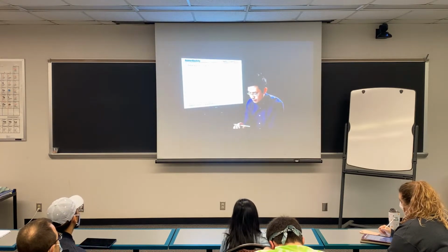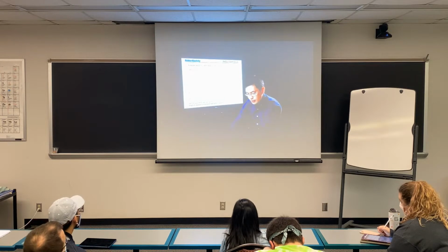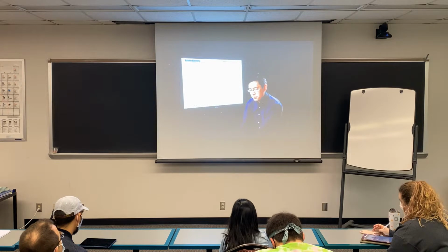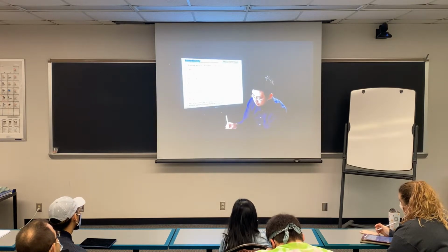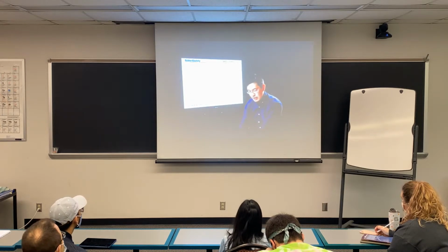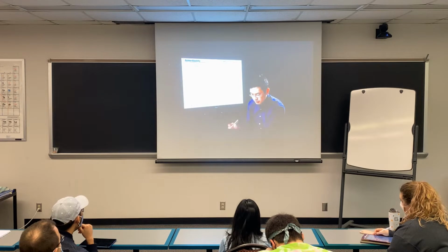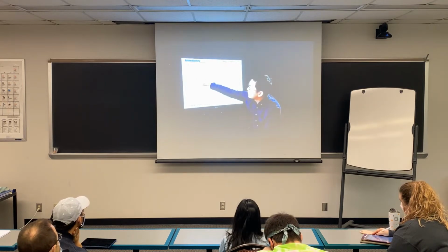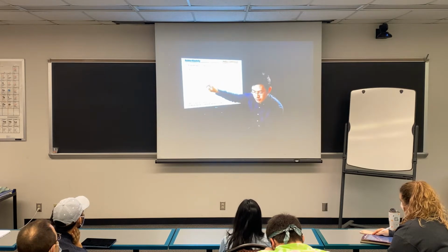Okay? So combining everything together, the most popular rubber elasticity theory modification is called the Mooney-Rivlin equation. The original term gives stress dependent on a constant prefactor and lambda minus 1 divided by lambda squared.